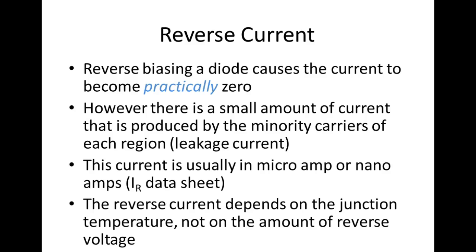If you get above it, then what's going to happen? The leakage current gets high. P is equal to I times V. Leakage current goes up, the diode's dropping voltage, power goes up, it gets hotter, right? Which causes the leakage current to go up, which causes the power to go up, which causes the leakage current to go up. So we get to a point where this thing is going to avalanche strictly from temperature. And we'll cause that to happen.